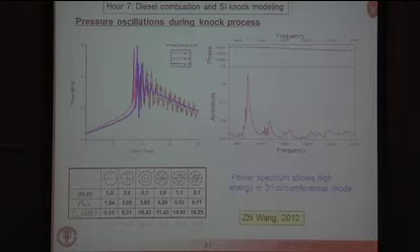So we took our calculated pressure trace here, passed it through an FFT, and got this plot here, which basically shows where the energy is located in frequency space. And you can see there's quite a lot of energy here associated with this third circumferential mode at around 15 kilohertz. These other bumps correspond to these other modes.